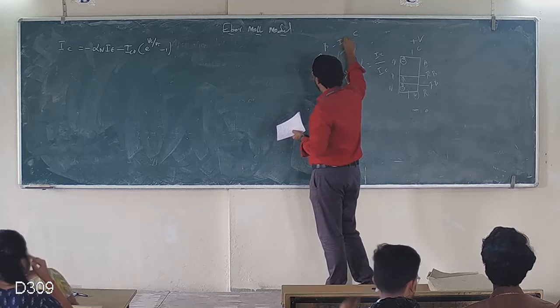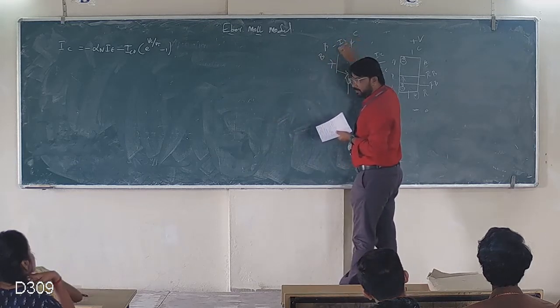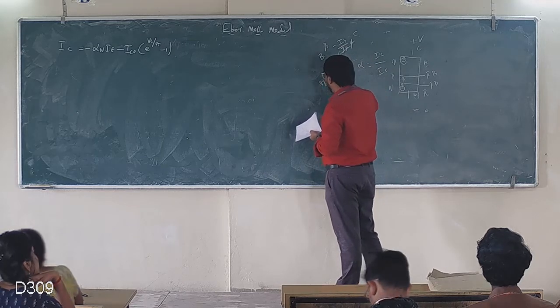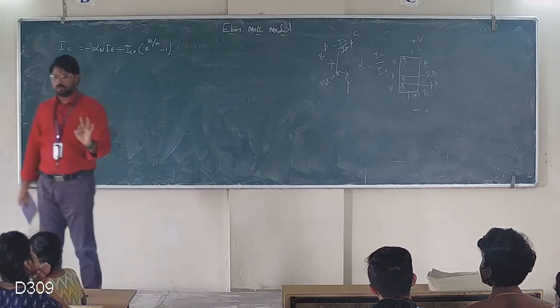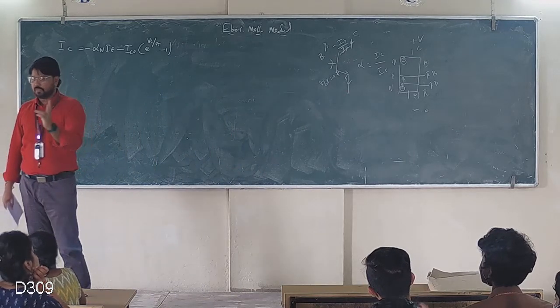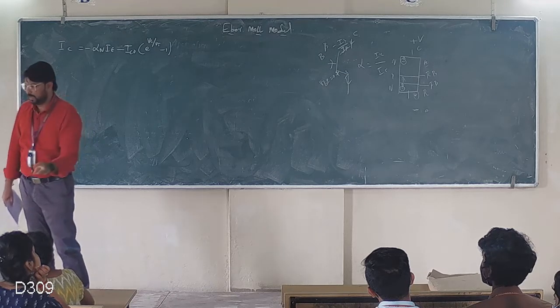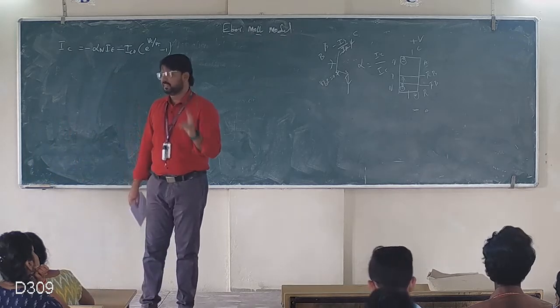Beta is equal to IC divided by IB. What is VBE? VBE is always 0.7. Remember, there are three fundamental parameters, like a date of birth: date, month, year. Alpha is the ratio of collector current divided by emitter current. Beta is the amplification factor.